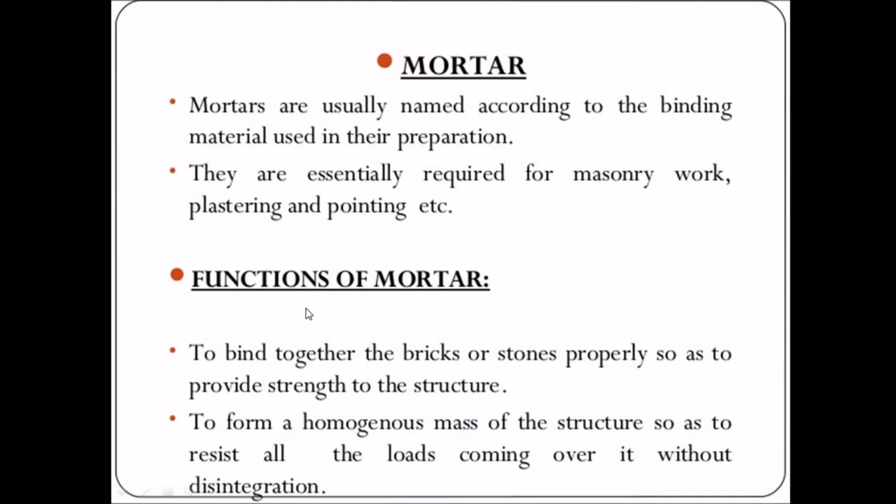Functions of mortar: to bind together the bricks or stones properly and to provide strength to the structure, mortar is used. To form a homogeneous mass of the structure so as to resist all the load coming over it without disintegration is another function of mortar.